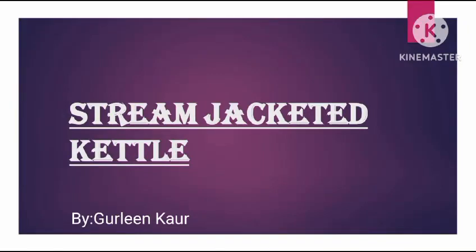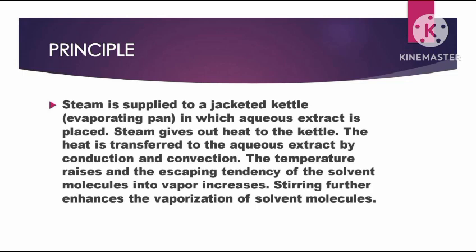Steam jacketed kettle is the most basic type of evaporator. It is a type of natural circulation evaporator and is also known as an evaporation pan. Talking about the principle, a heat transfer mechanism is involved in this evaporation process, which is basically conduction and convection, which transfers heat to the extract.